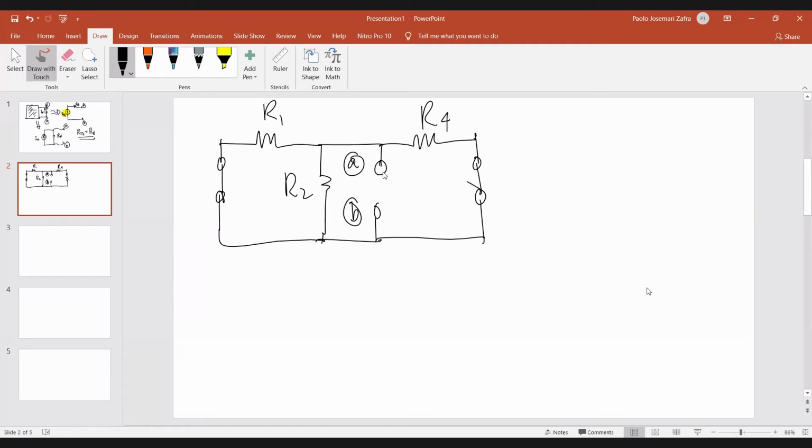Now in the experiment, what we can do is excite this circuit with a voltage source having a fixed value of 1 volt, then measure the current and take the reciprocal for the equivalent resistance. So that's how we solve for that.